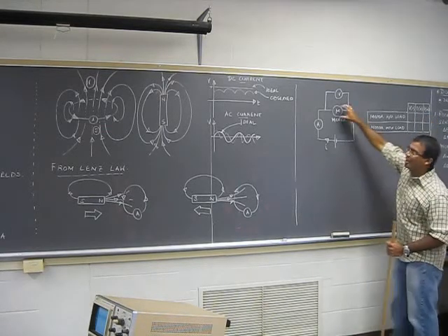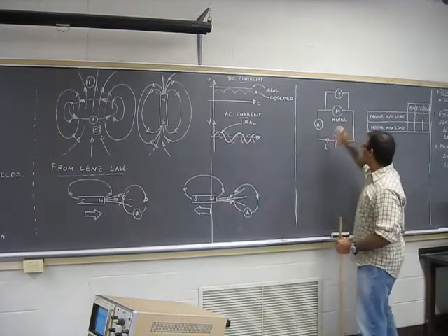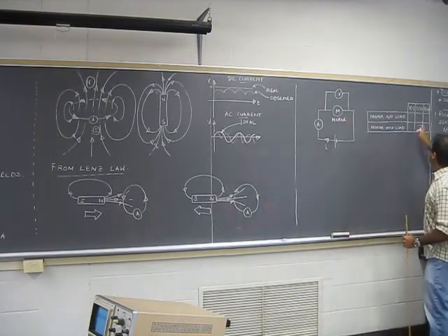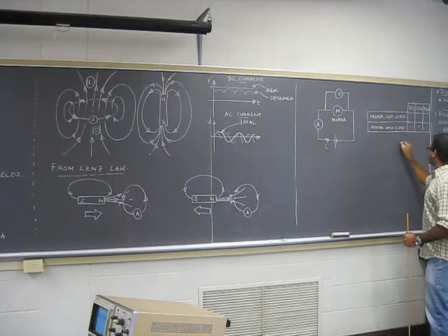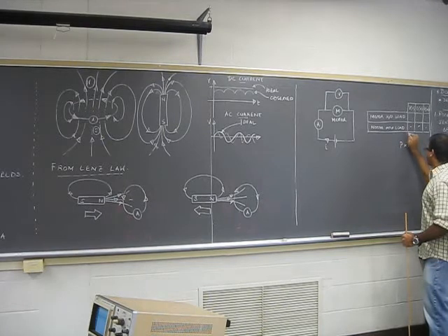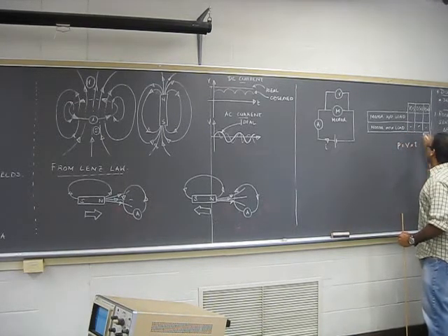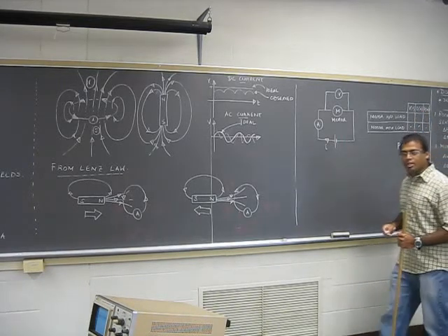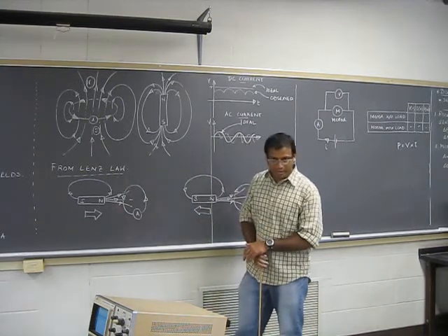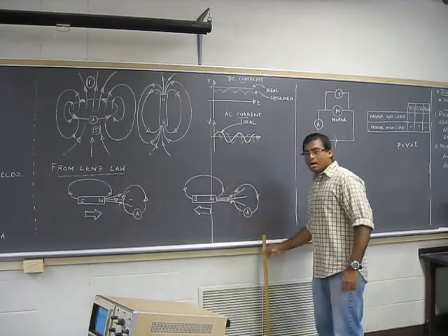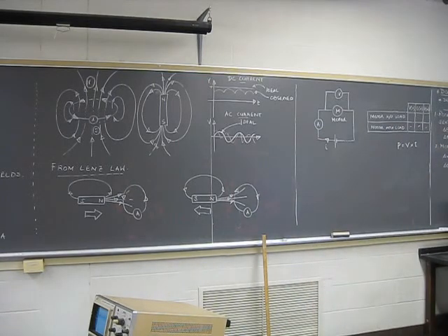And then we will apply a force. We will try to hold the motor down. So in other words, we will have a load on the motor, and then again you will record the voltage, the current, and then the power, which is equal to V times I. Now remember to convert the current into amperes, because what you will need is milliamperes. Okay? So let me start one of the tables, and then we will start together afterwards.